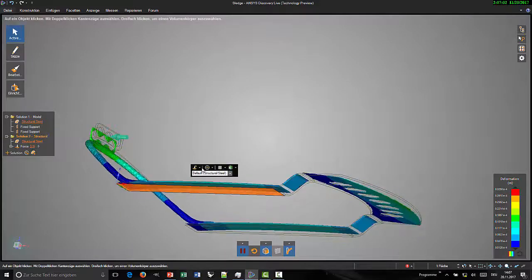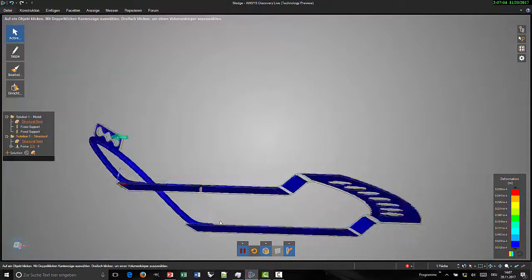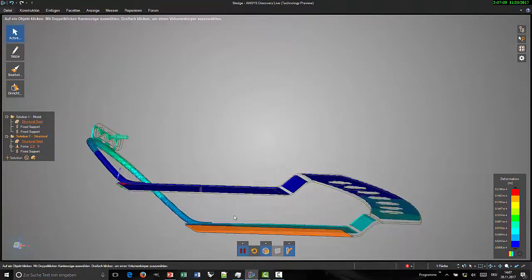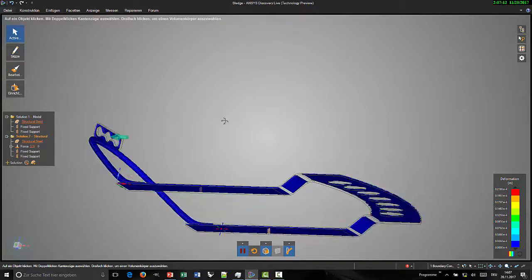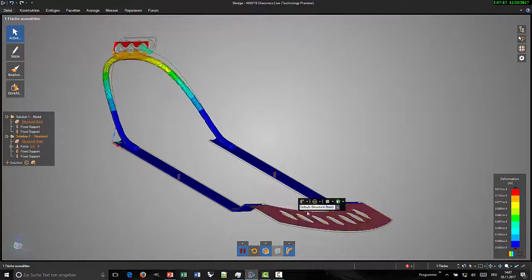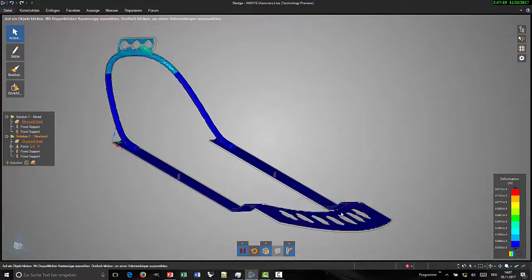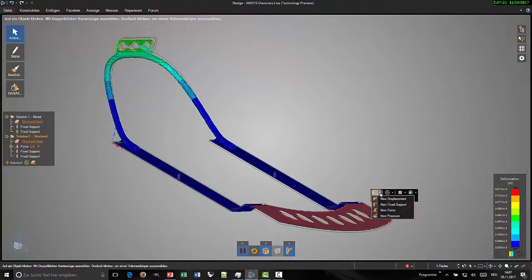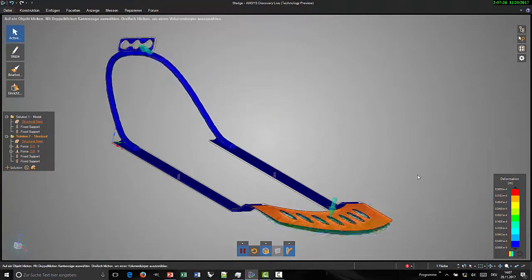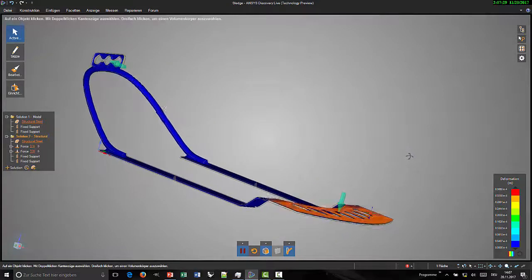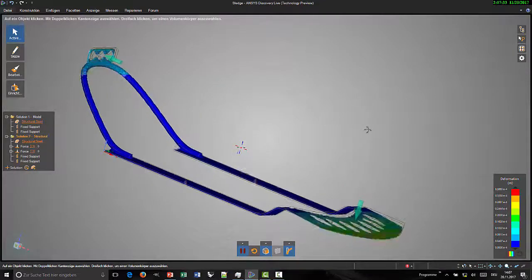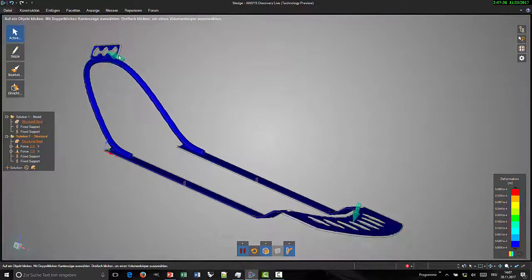Now we will do that here, and again say this might be fixed, and on the other side as well. And then of course we know that basically only the upper part, after a while, when the iteration is done, will deform. And on the back side, I think we haven't done it properly before, we will place again a force boundary condition facing downwards. You see immediately the arrow where the forces are supposed to direct, and here you see how these things behave with these two load boundary conditions assigned.